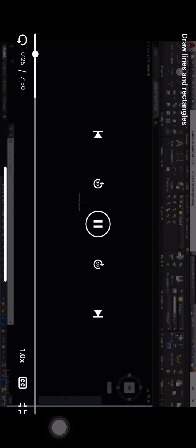screen. So when you download lines and rectangles.dwg from the website as an exercise file, you can see it's an empty drawing. The model space is empty right now. The only thing I will ask of you is make sure that you go to the Home tab on the ribbon, go to the Layers panel, click on the drop down, and just make sure you're using the Object layer as your current drafting layer. So we're going to have a look now at drawing lines and rectangles.